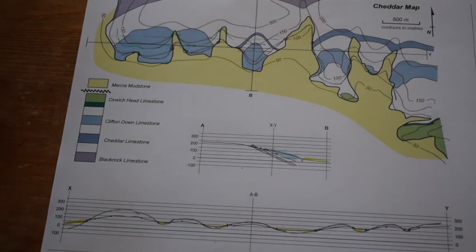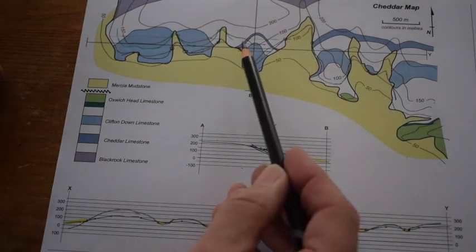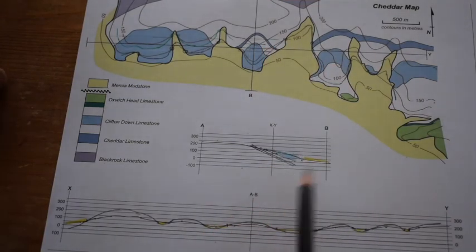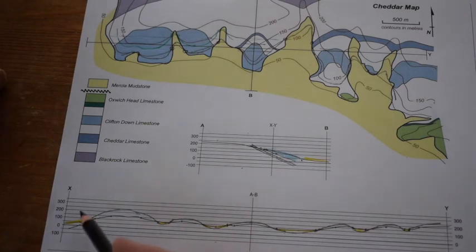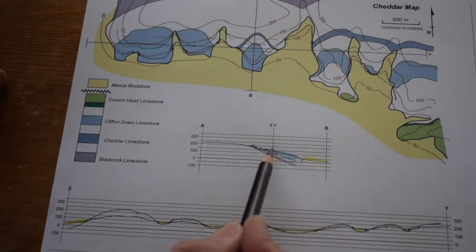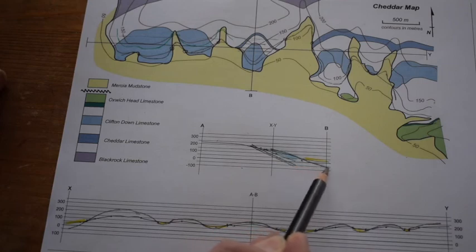We can just make sure this is all working, can't we, to honour the structure contour patterns and the section. We can take this longitudinal section where we suggested that the unconformity here was at elevation just over 150 metres on section AA, so we can take that information and say the unconformity is there. So here goes our unconformity, somewhere like that.